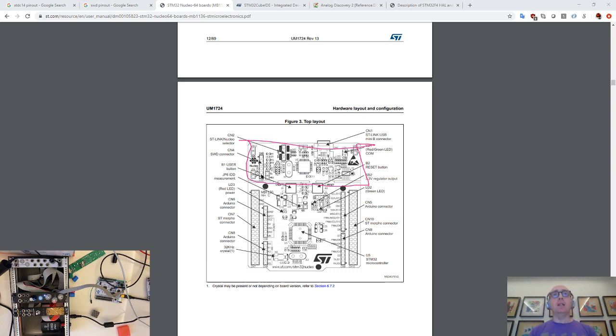Now, those pins are kind of annoying. Oh, and then it also has a separate 2-pin header that's slightly offset and not on a grid, thanks ST, for a UART to transmit and receive for serial. So you can use PuTTY to connect and send strings of text to and from your board. So I built a little tiny adapter.